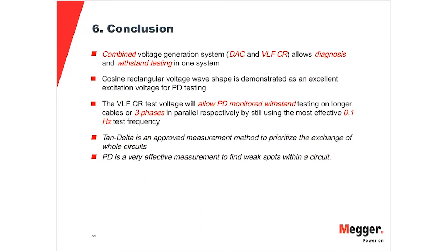So what are the conclusions? The conclusion is that the combined voltage generation system, which consists of DAC and VLF cosine rectangular, allows diagnosis and withstand testing in one system, reflecting the reality. The cosine rectangular voltage wave shape is demonstrated as an excellent excitation voltage for PD testing. It reflects the reality. That's very important.